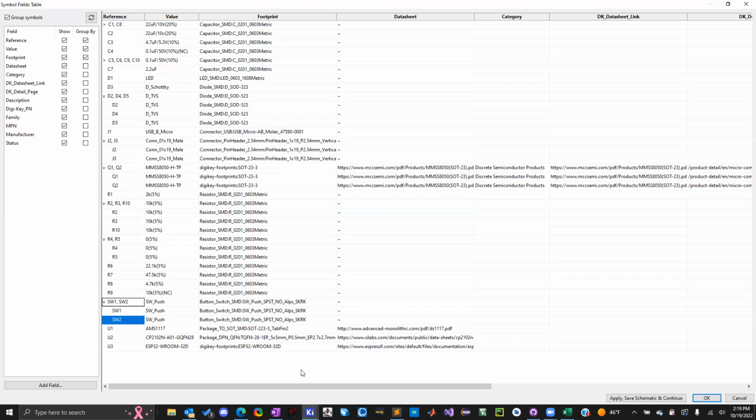Yeah, but some of our components are smaller than a needle. This is the actual mainstream developer kit being sold, with one slight adjustment based on some online user feedback. There's a couple of forums about it, but some people are having issues with the auto program functionality. So I added the capacitor between the enable and the ground to help fix that. Hopefully.